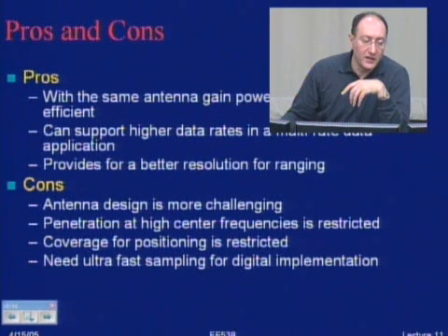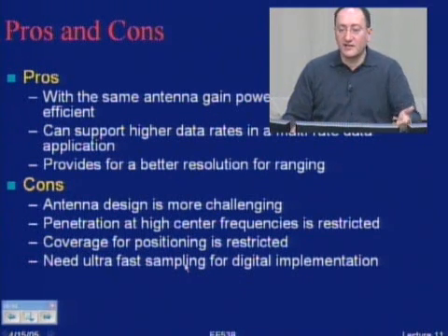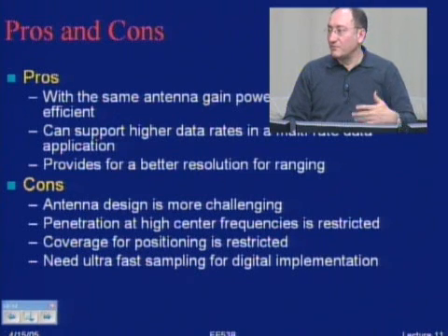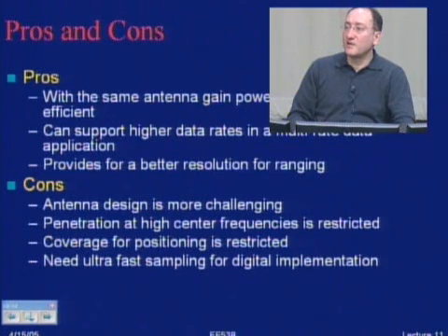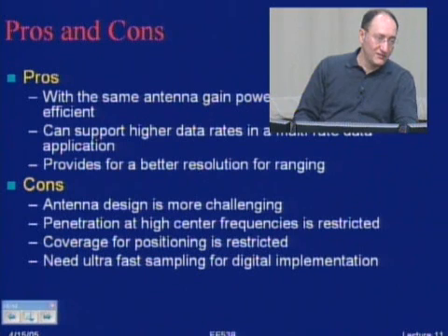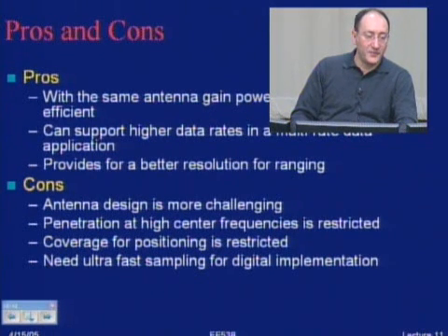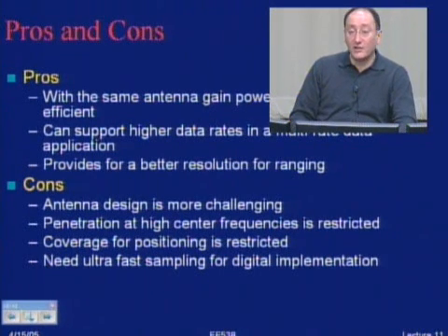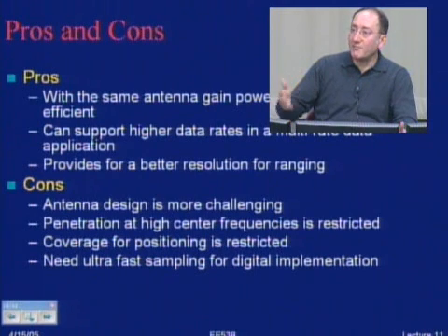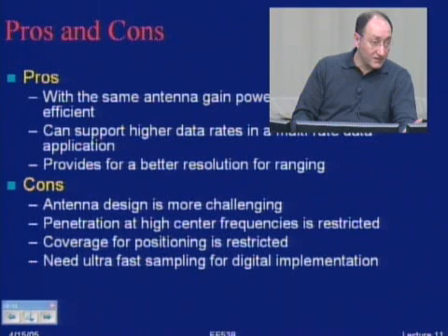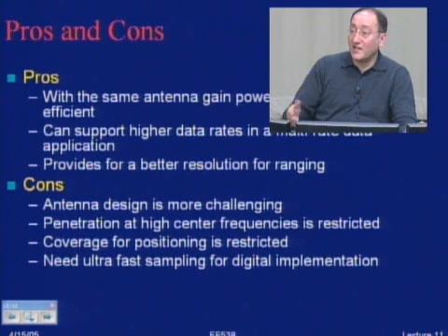Then, if I'm designing these things, these days everybody wants to design digitally because it's less expensive and more controlled. With ultra-wideband, I have to sample at least at the Nyquist rate, twice the bandwidth. So that's a challenge.